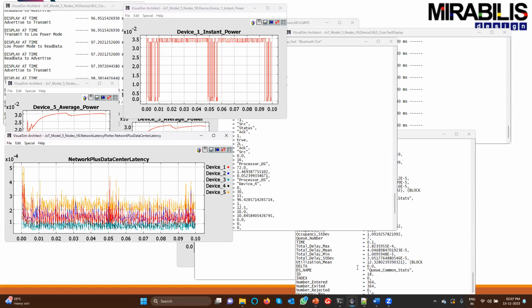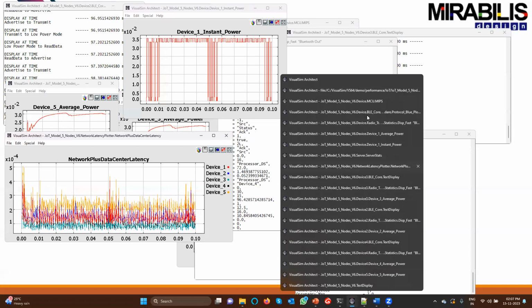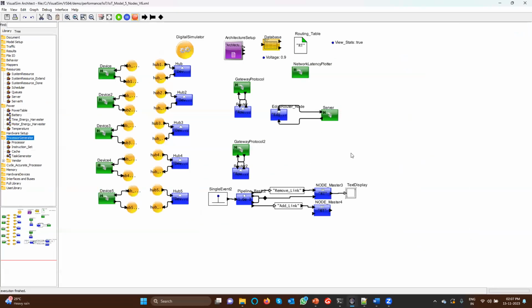So you're able to see everything in a single view: the performance, the power states, the instantaneous and average power, the statistics on latency. All of those are captured within a single module. This forms a very important aspect of your power modeling because now not only is the power system not working in isolation, but it's working in the context of the entire SoC or the entire system.